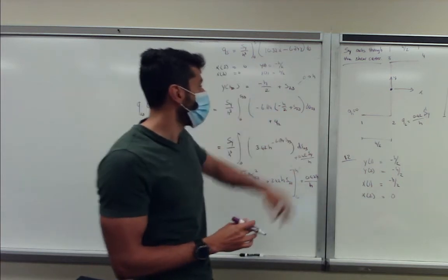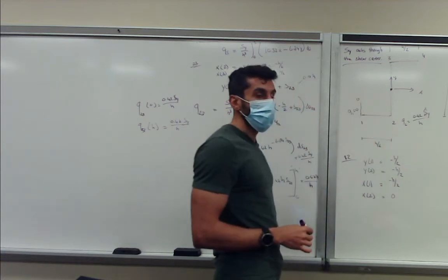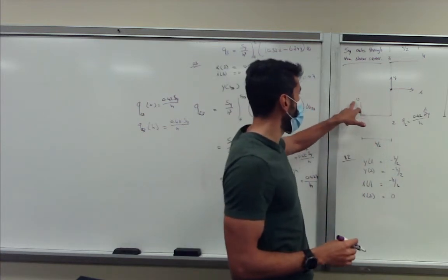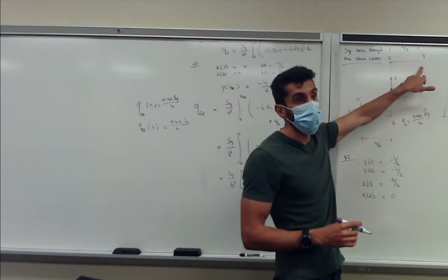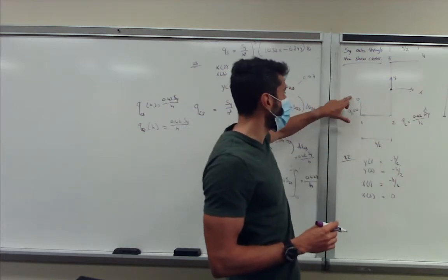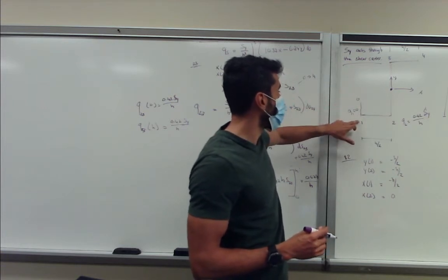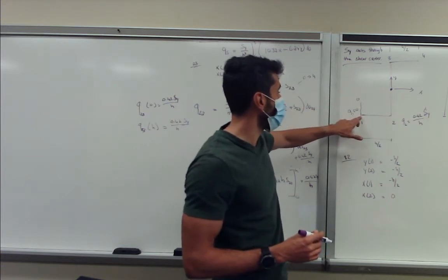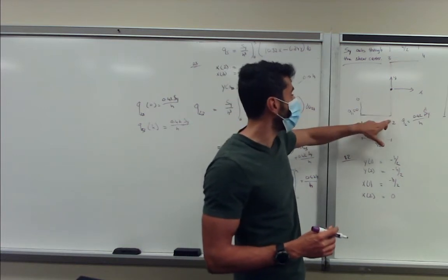Then we would add, say for example, the structure would be like this, right? We go from 0 to 1. Then you still start with 0 because you know that the shear flow at that position is 0. Then you can calculate, say you start at 0, Q0 is 0, but Q1 is no longer 0. So for segment 1, 2, you add Q1 to it. And segment 2, 3, you add Q2 to it.